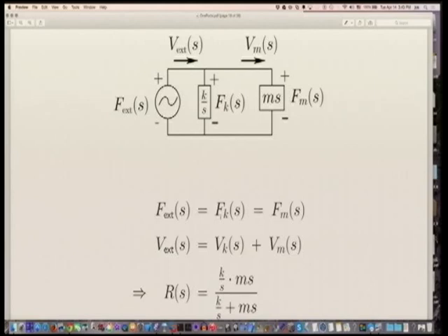Ah, yes. So that's why you can say, let's consider the port impedance of force external and know what it is by looking at the impedance it sees. So if we kind of chop force external out of that diagram and then look at what impedance there is between those two terminals without force external attached, that's why we get this port impedance.